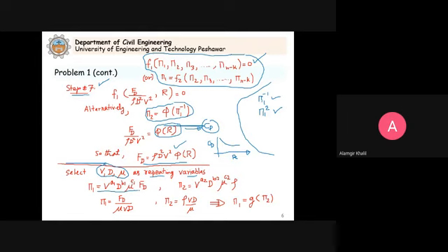You see mu is now repeating, and this will be the pi 2 group with mu, V and D. When you solve the problem like we did here, you will get this as pi 1 and this as pi 2, which is again a Reynolds number.